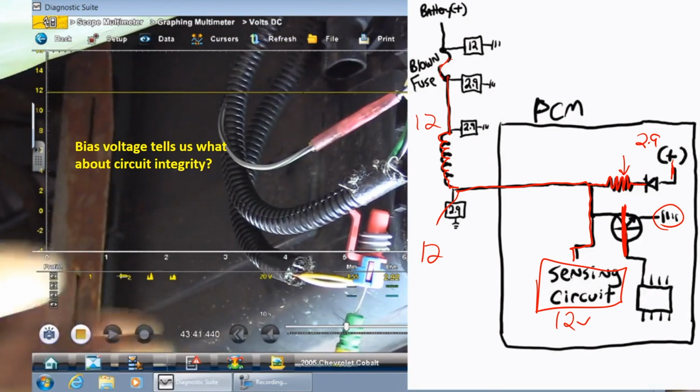Or it could be what I said. Maybe there's no diode. I don't know. I just drew it this way. Maybe there's no diode, and this is 12 volts. And this is a 500 k ohm resistor. And why am I seeing 2.9? Because my voltmeter dropped it. If that was the case, and there is no diode, I have 12 volts coming this way, and I have 12 volts coming this way, am I going to hurt the computer? No. We'll keep the diode in there.